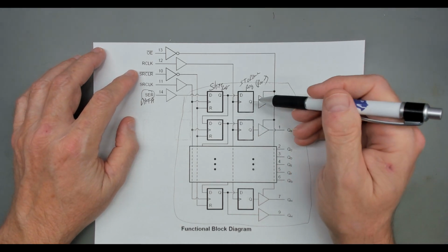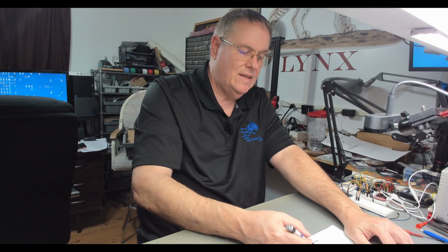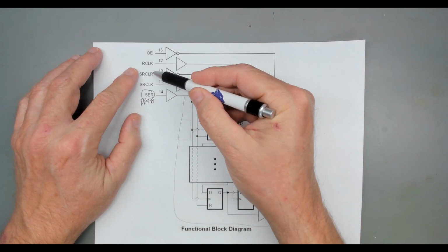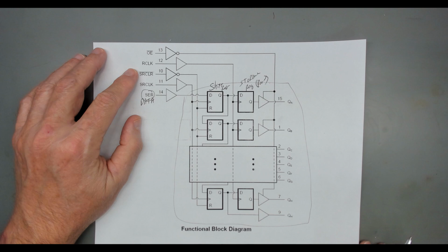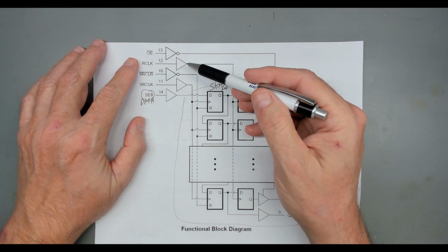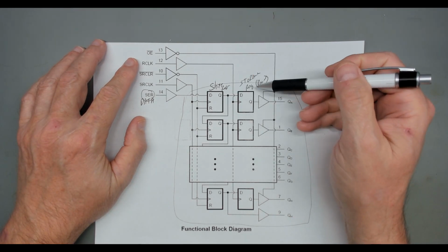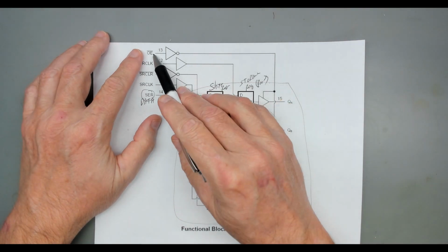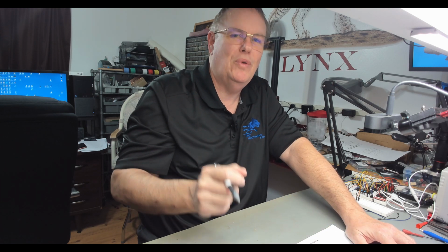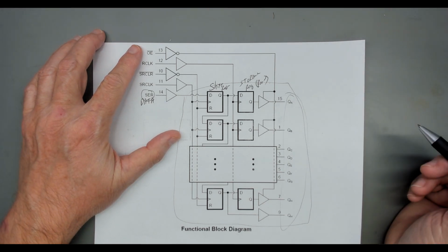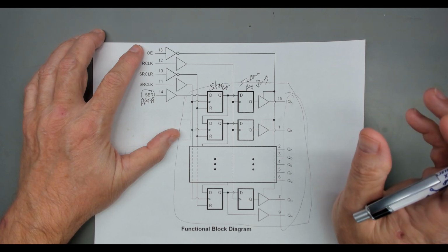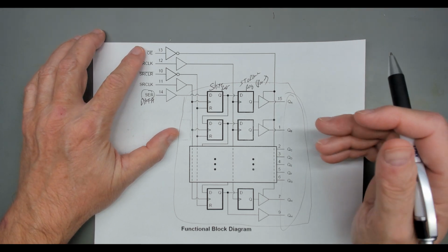You have a shift register clear line. And what that does is whatever data is in the shift register, it clears it, all of them, in one shot. The little line over this means that to do this, you pull it low. If you pull this line low, all of these shift registers clear. They go 0, no matter what's in them. You then have the register clock, which is the clock to clock data through into your storage registers. Then you have one more line up here called OE. Again, notice the line above means to do what it's supposed to do, you pull it low. And that is your output enable. That turns on these outputs. If you pull this low, these outputs do their thing. If you pull it high, it turns them off.